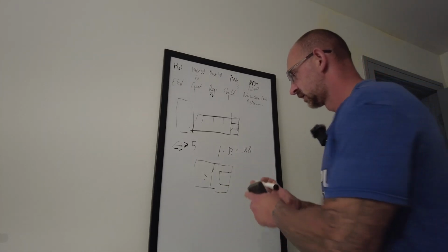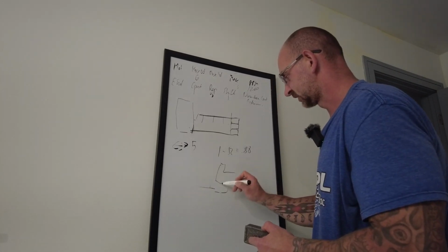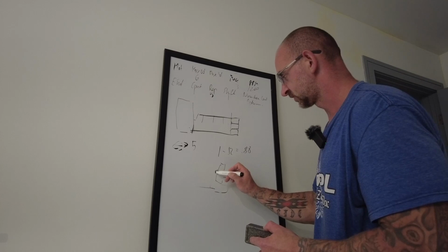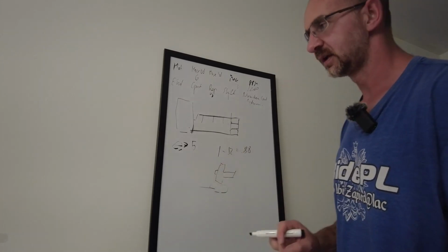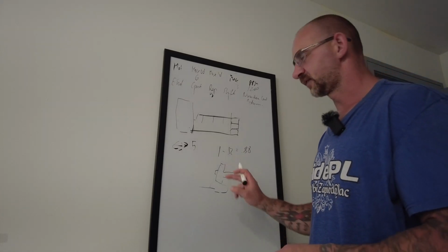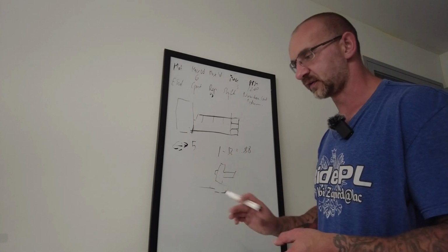And it doesn't matter how it looks. I mean, it can look like this. Once you break it off, you're going to have this little nipple, so you can grab it here or here and then machine it off, right? Or if you don't want to machine it off, you can get away with it, you can probably grind the back of it and just lap it.